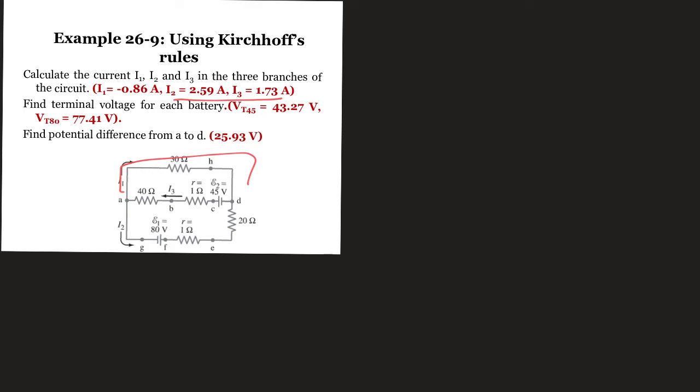Once I confirm the direction is correct, or I have fixed it to the correct direction, I'm going to see whether it's charging or discharging. For EMF2 here, the current moves from lower to higher potential. If you find it hard to decide whether it's charging or discharging, you can imagine the current moving like this inside the circuit, from higher potential to lower potential, which means this one is discharging.